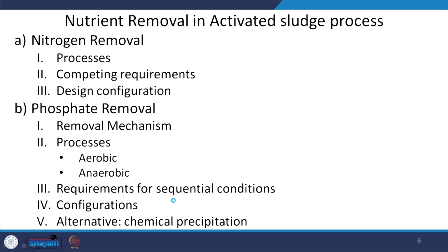So, let us move on to the next major aspect. Until now, what have we removed, right? Let us just take a quick recap. So, preliminary treatment, first we want to lift the water from one head to the other. Okay, so that's one thing. And what else do I want to remove? I want to remove particles that can mess up my machinery and such, right? I'll have different types of screens and such, yes. And then I will remove the heavier particles, grit, which is relatively inert, right? And this is during our headworks or preliminary treatment.